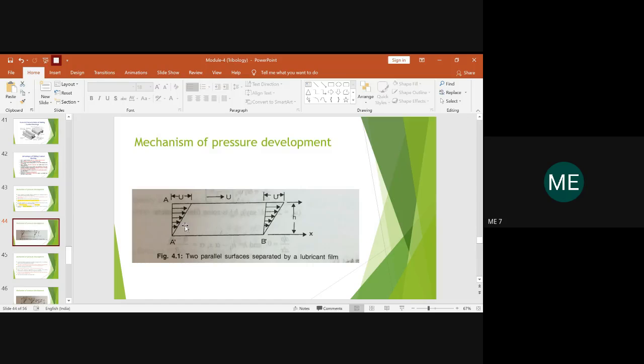Based on that theoretical aspect, we have assumed that the velocity distribution in this triangle will be equal to the velocity distribution in that triangle. It would be the same if you take one more section, C C dash, and here also the velocity distribution will be the same for the given fluid film thickness. So these prerequisite concepts you should be very clear about.